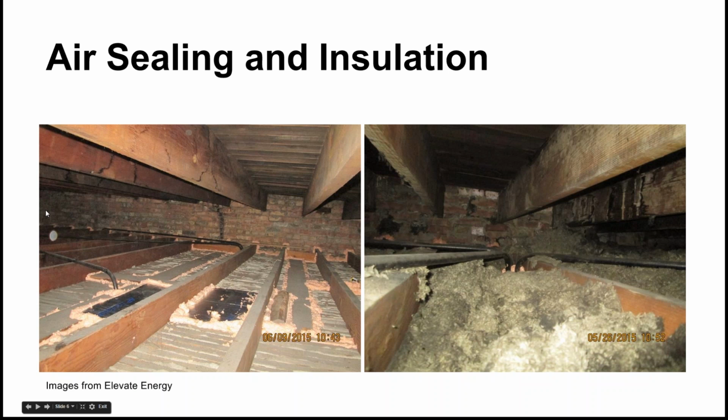What I have here on the picture on the left is a building that I helped retrofit. I didn't do this work myself, but you can see all of this pink stuff here along the bottom in these little areas. This is in the attic. Basically, this is spray foam that was used to seal any parts of the building that were causing infiltration. And this is at the top part of the house, so it's reducing the stack effect and preventing air from moving through it really quickly. That can be done at many different parts of the house with many different types of materials.